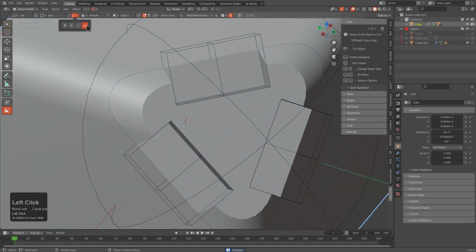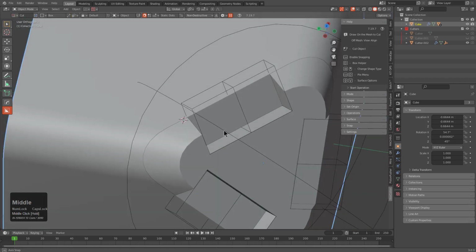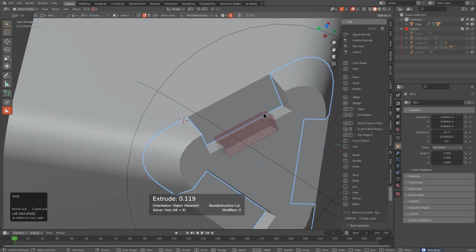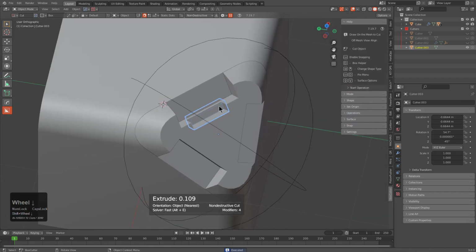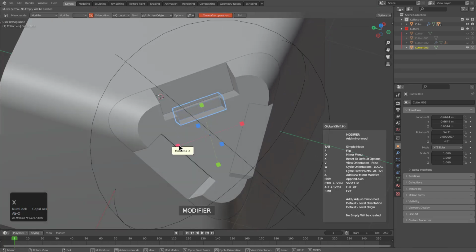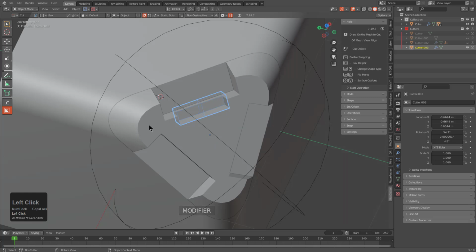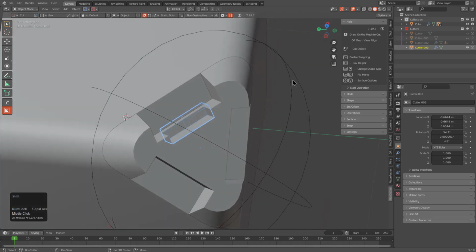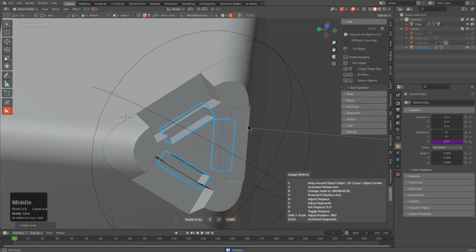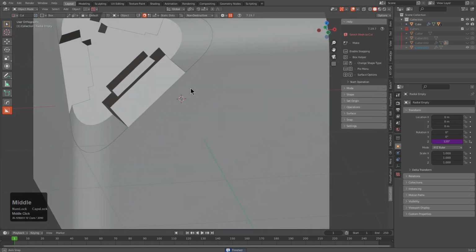So in this update, we improve the ability to use the active element origin set for Boxcutter, meaning that if we draw a shape and we hold shift in order to keep this live, we now have the same origin as the target that we've cut from and the same rotation, meaning that we can now mirror this across itself without having to select a target. And then we're able to just select the same empty and just simply radiate this and perform our array without any sort of issue.